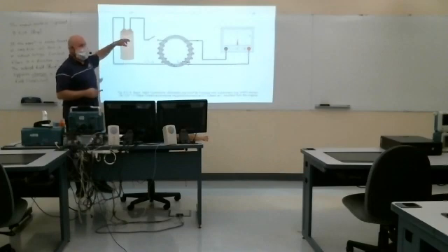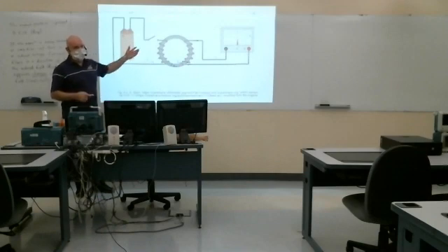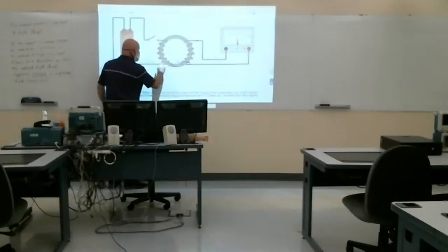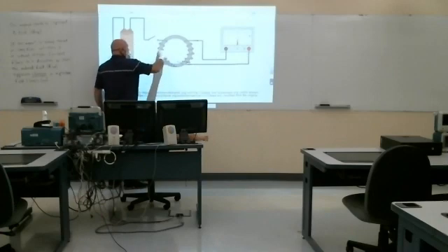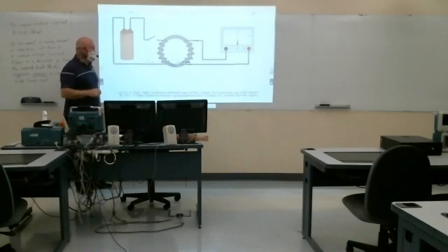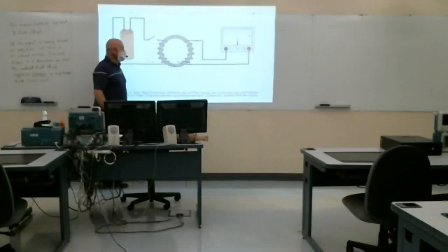Now, change the polarity of my voltage source, everything changes. Change the winding direction on either coil, we have to go through the analysis. Change the winding direction here, so it comes over the top now. Then my impressed field would actually be going the other way with the same polarity voltage source, right? And so everything would be different.